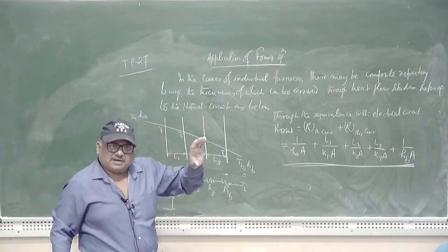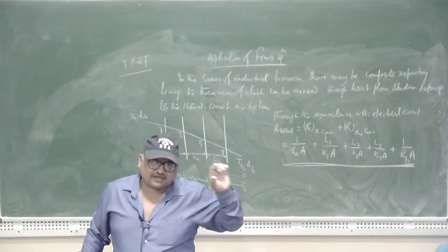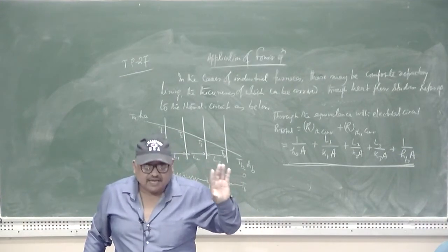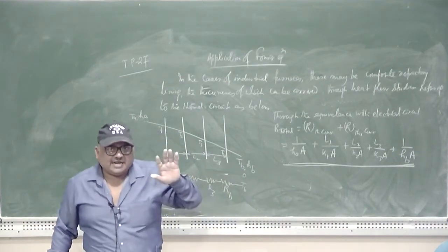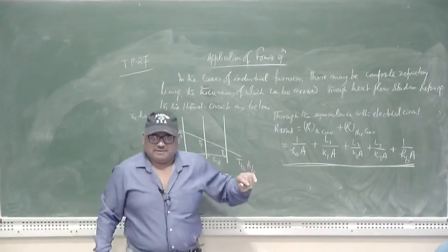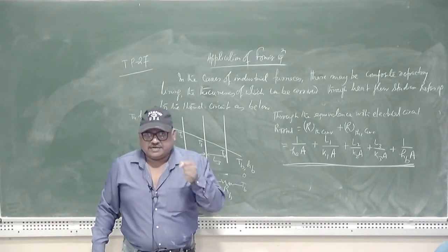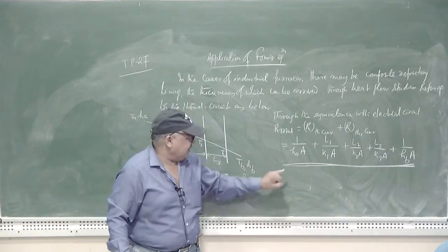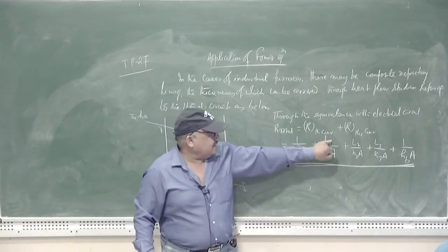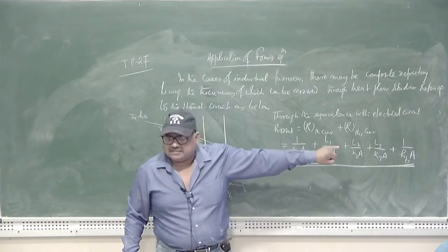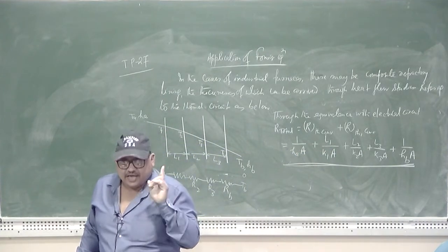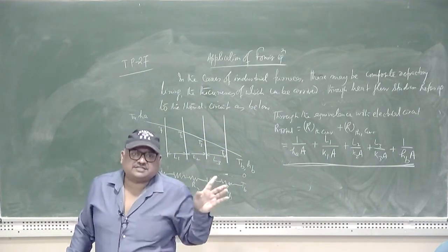If you have to arrive at a particular heat flow rate or heat flux in the case of any industrial furnaces, then you can easily adjust it. You cannot adjust the Ha and Hb values, but the quantity which is in your control is the thickness of the refractory lining. That is, by altering the values of L1, L2 and L3, a desired value of heat flux can be achieved in the case of any industrial furnaces.